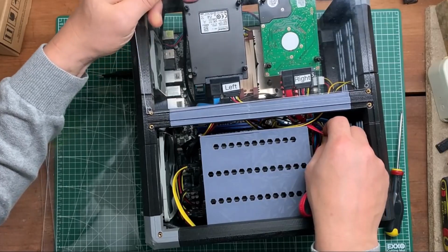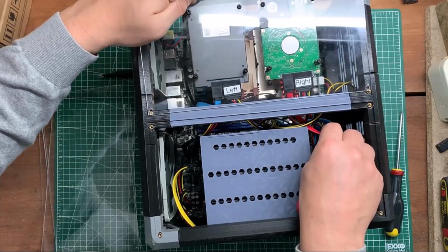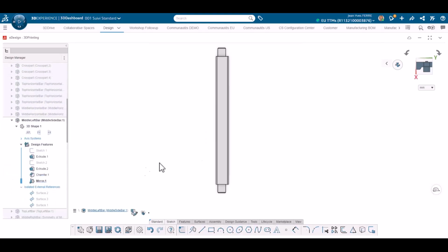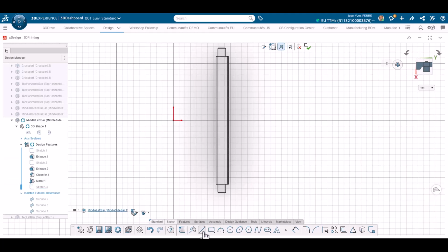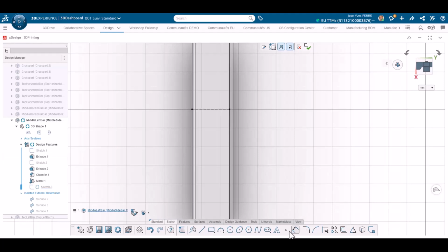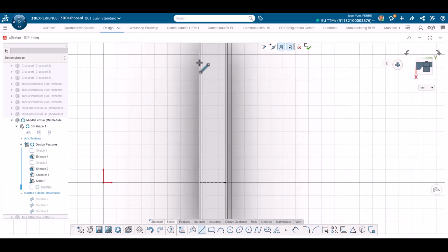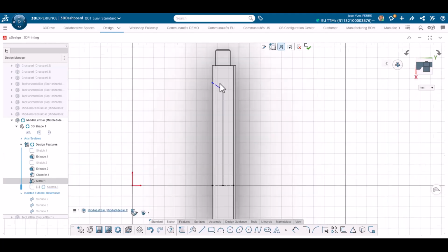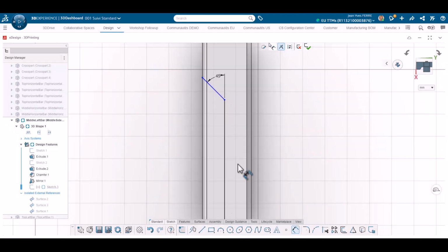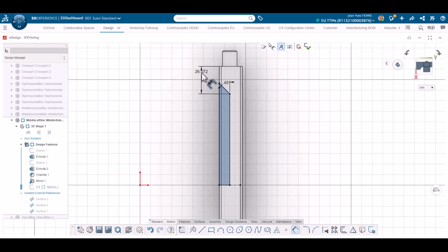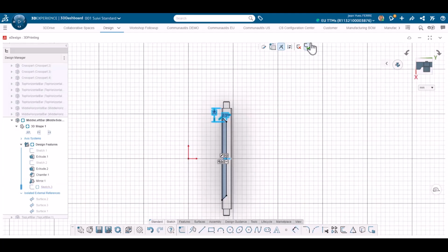As explained before, I couldn't quite fix the SSD panel because of cables I didn't take into account when designing. So I will solve this issue by making a recess in this middle bar. This is not a bar that will be loaded the most, it's just there for rigidity and fixing panels. So there should be no issue if I remove some material. As the first prototype was strong enough, I decide this will be okay. This is the kind of assumptions you need to make all the time. However, for critical ones, you can still check your assumptions with the simulation app. This is not the goal of this video, but it exists.